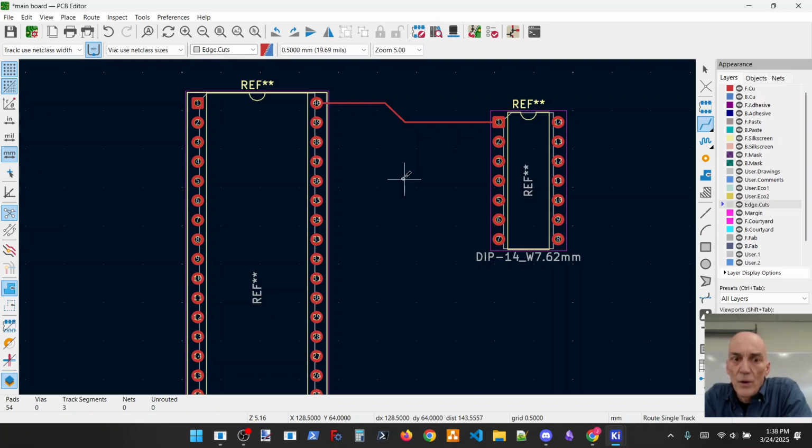So my thoughts are for the claw machine again, that we've got pictures of the board. We've got the data sheets. Mostly, I think we've got all the data sheets collected on that. And so, from the pictures of the board, we could figure out, okay, there's some kind of 40-pin chip here, and there's an 18-pin chip here, or whatever. Put those sockets on there and start tracing out the connections. Then once we have that information, we could say, okay, if this was a whatever chip and this was a whatever chip, these pins would do this, and they would be connected, and reverse engineer it.